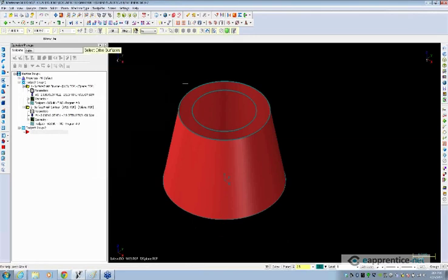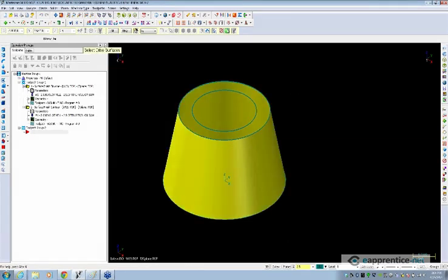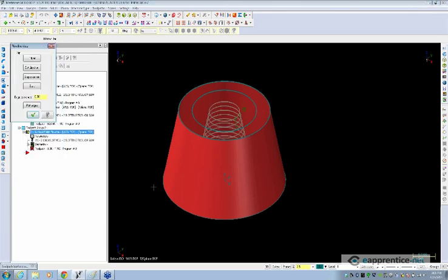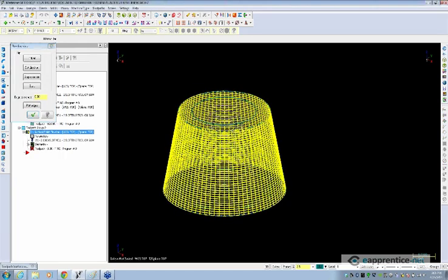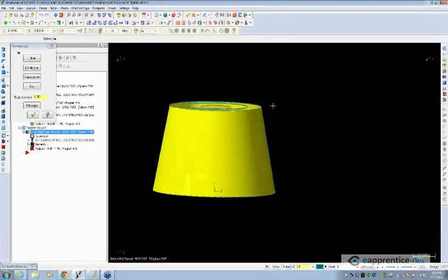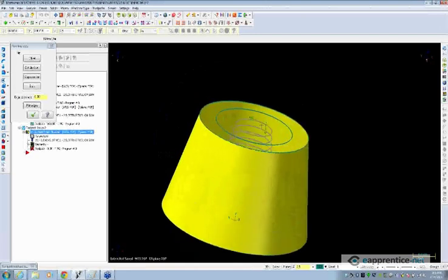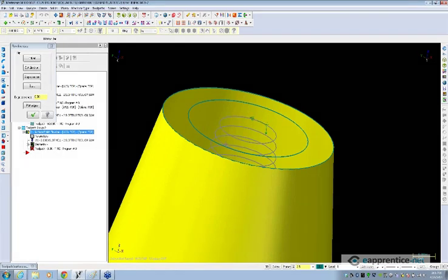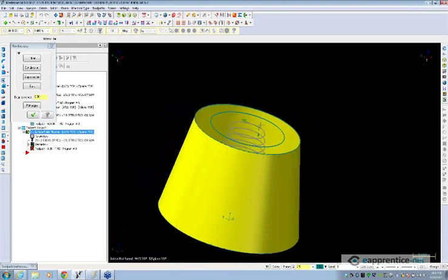Flowline. I'll select this surface as my drive surface, and now we're going to go and look at the Flowline curves. When I click on the Flowline button here for flow, you can see that Mastercam is now going to machine on the inside of the surface here. And this arrow tells us the direction that our cut is going to go and our step is going to go. So in this case, our cut direction is cutting, kind of spiraling around the surface or slicing it, and then our step direction is stepping down, and you'll notice we're starting from the top.